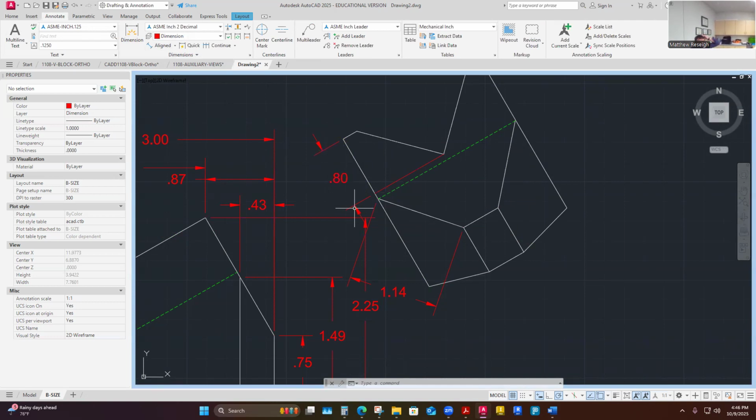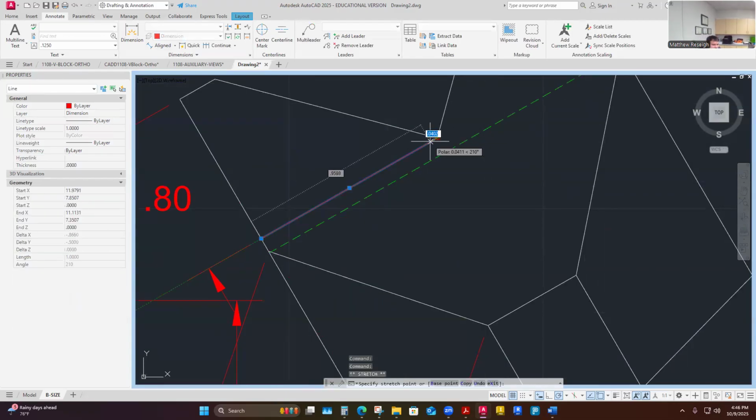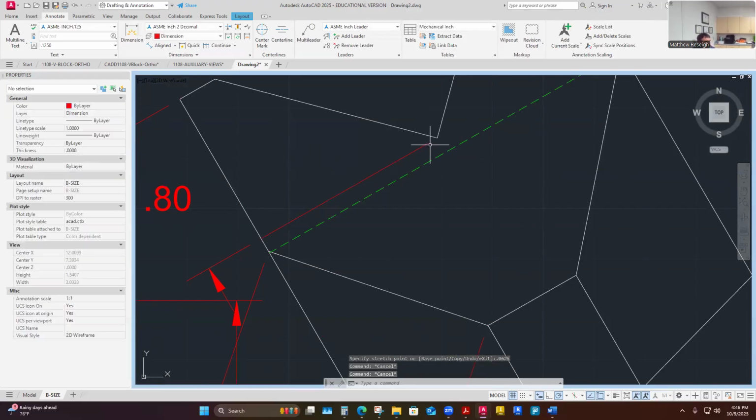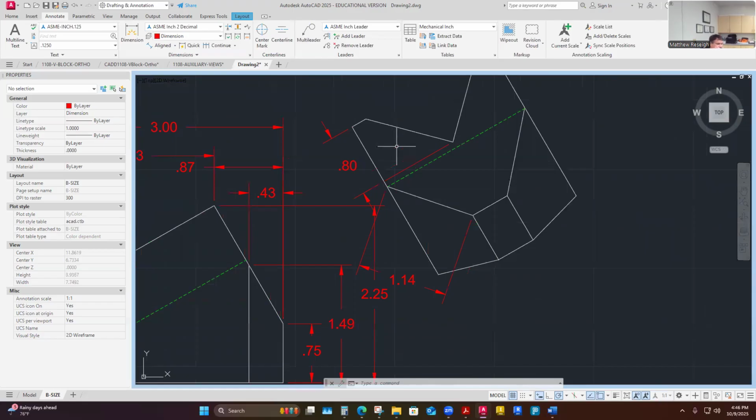So I've kind of done this, and it's kind of a get-it-done method. But I'm going to pull this back away 0.0625. That's, or 0.6 is fine enough. Essentially, our dimension styles were set up to break away a 16th of an inch from the object edge on all the others, and that's following that pattern because I'm actually using it as an extension line of sorts, even though I have a breakaway of it here. It's a little bit of a hack, I guess.